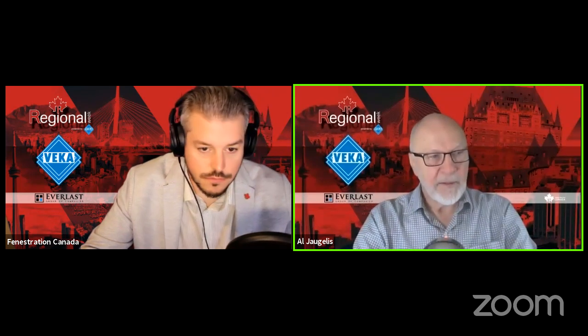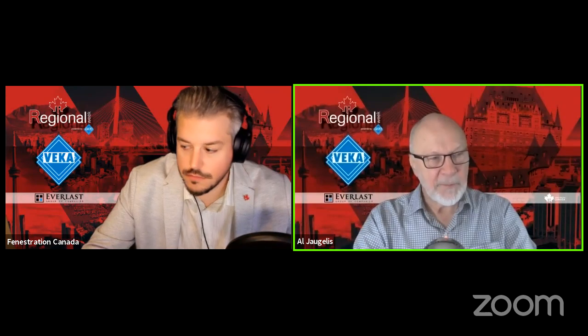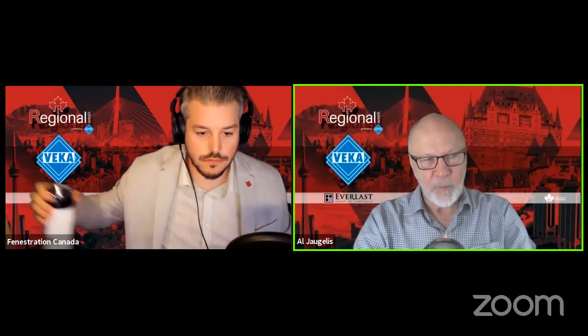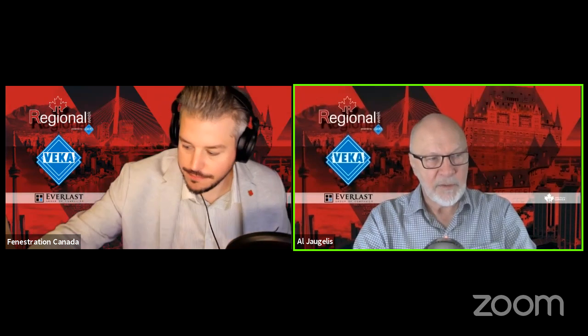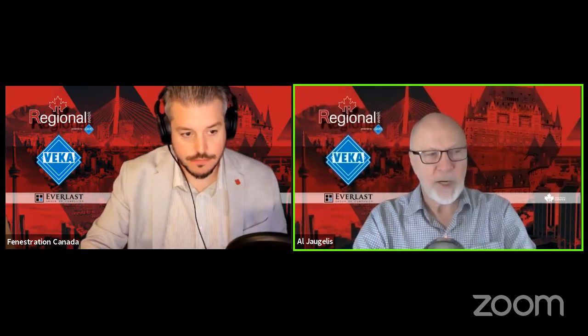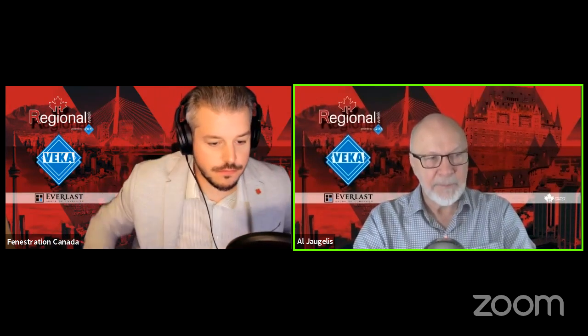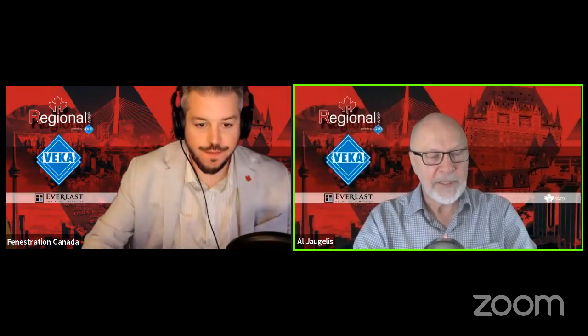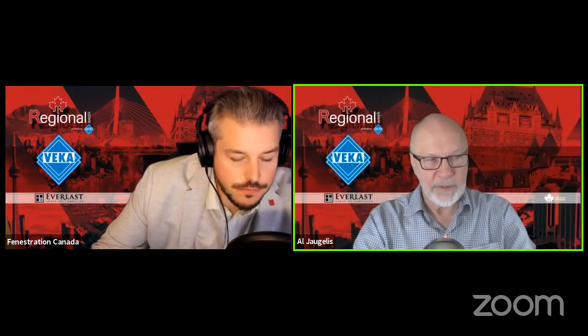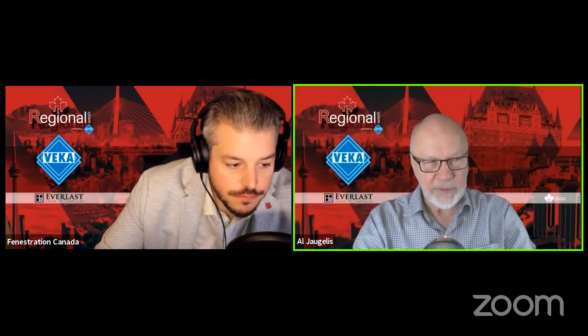And I am not sure quite what they mean. I don't know if in Canada anyone does actually build doors on site from a kit of parts. Usually these doors are highly fabricated when they come to the job site, and there is some site assembly, but the critical components related to weather performance are usually factory level work.